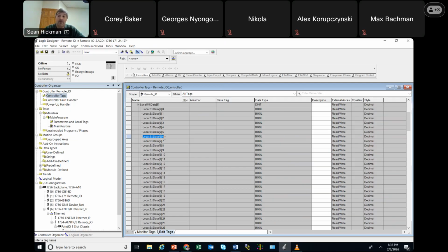Okay, so now you're like, man, that's a lot of mapping. There's 122 times 32 or whatever. That's a lot of mapping. Well, there are different ways to do this with copy and synchronous copy. You could write subroutines to do it, stuff like this that you could just import every time, or add-on instructions. If you take PLC 2, we'll talk about some better ways to map this.